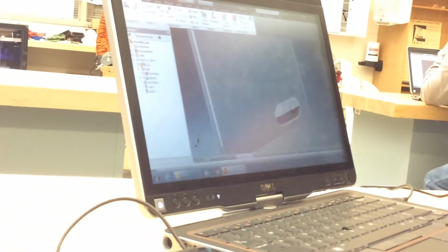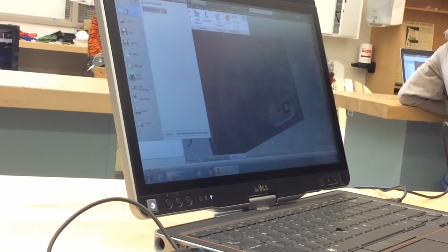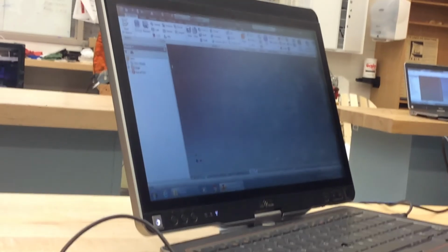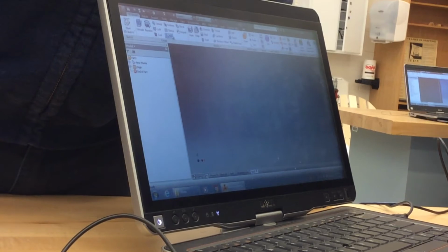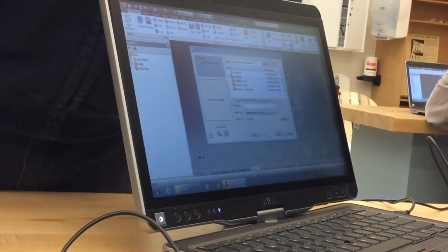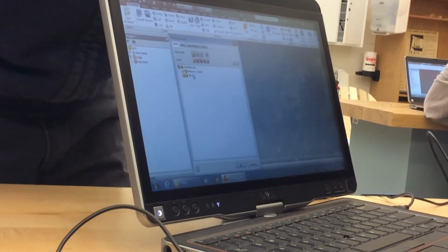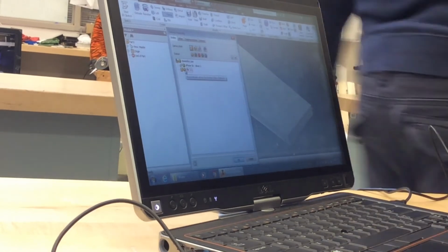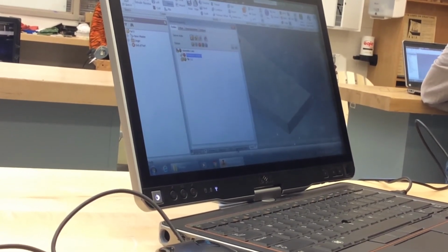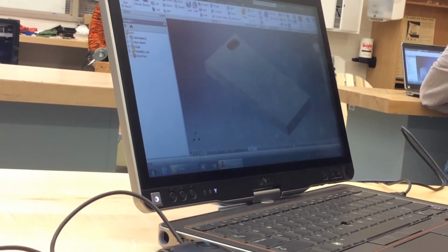Now, last step to create our phone case. I'm going to grab a new file, a brand new file. This new file is going to be a new part. This is our case right now. So I have to derive the part, okay? There's derive. I want to derive it from our assembly, okay? And I want that mid-step file, whatever we did in that mid-step, to be positive. I want the phone to be negative. So now we have that negative. Click OK. And now we have an indentation of that phone here.